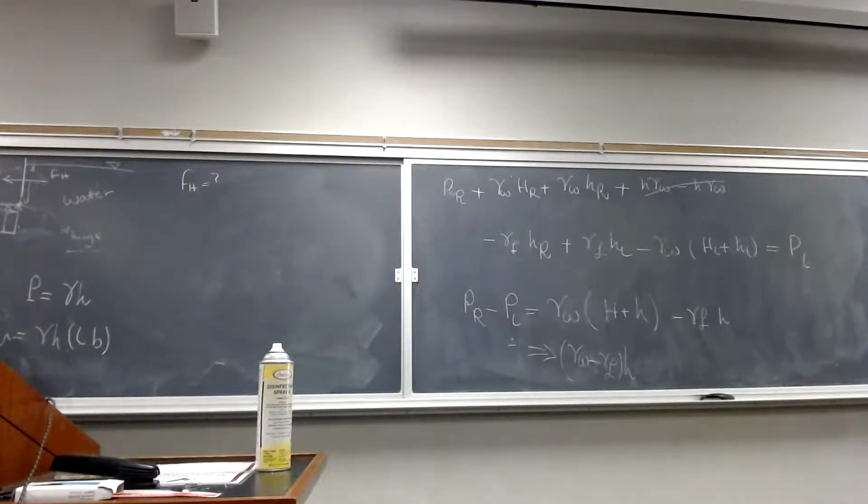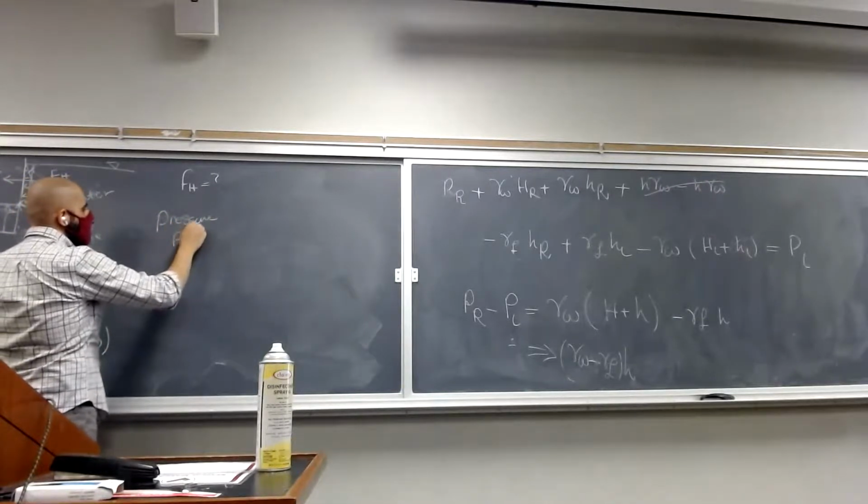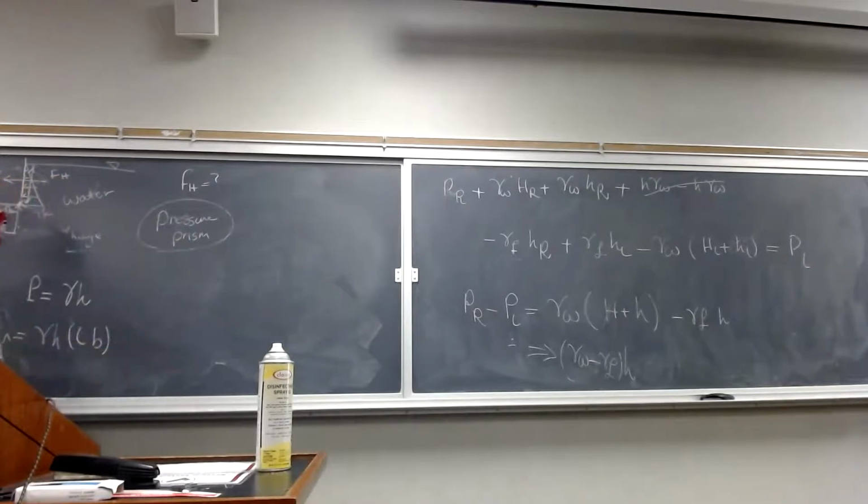Horizontal force, we have the hydrostatic pressure here. But your pressure is increasing from a value 0 to a value gamma H. So we're going to get gamma H here and 0 at the top. If you recall, we can find this hydrostatic force from the pressure prism analysis we did in the previous lecture. If you do the pressure prism analysis, you essentially have to find a volume that this distribution makes, right?